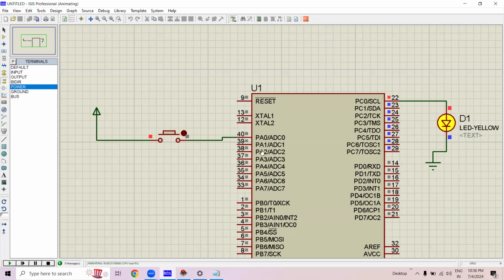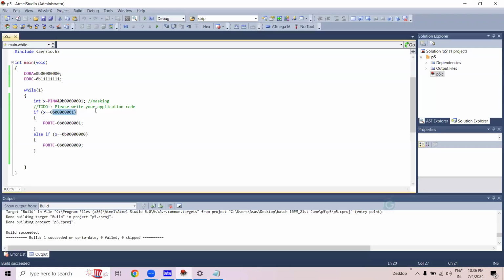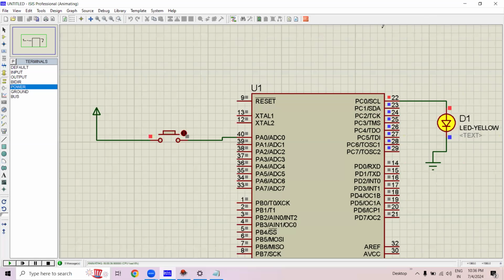So we can see on the right side of this button is gray logic, which we are passing to port A0. That means there is no logic at port A0. It's null. So that is why there is no condition which is satisfying, because we have only two logics in binary, the 1 and the 0. The 1 is on and 0 is off. So 0 is not coming here. And if 0 is not there, then definitely the button or the sensor will not respond in a correct way.